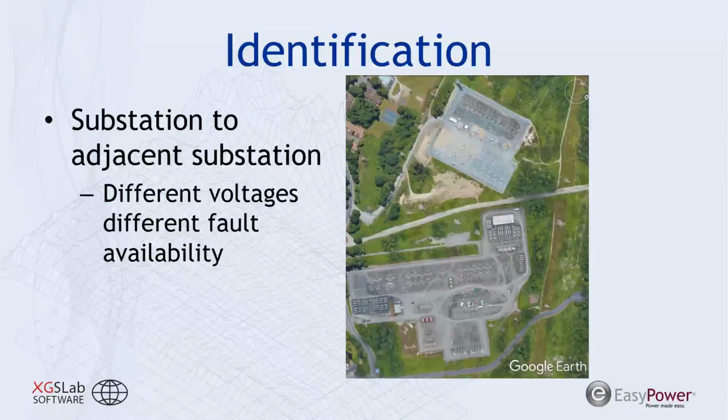Another type of issue we see is substation to substation transferred voltage. Often when we're doing a grounding system analysis, we look at a substation's grounding system in an isolated view. And the reason is that this would often produce a more conservative result because the smaller grounding system can have a higher grid impedance and therefore you can have higher ground potential rise.